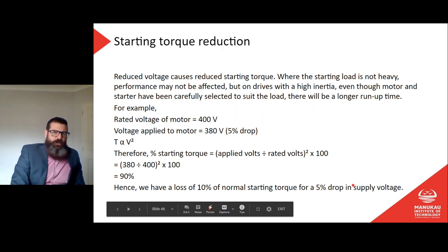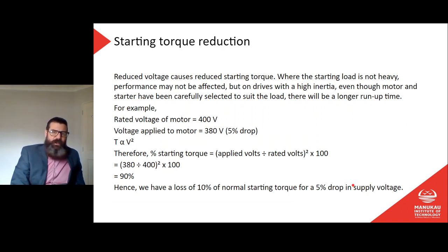Starting torque reduction. Reduced voltage causes reduced starting torque. Where the starting load is not heavy, performance may not be affected, but on drives with high inertia, even though motor and starter may have been carefully selected to suit the load, there will be a longer run-up time. For example,